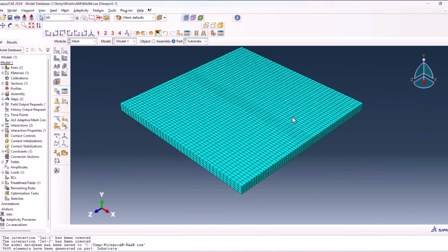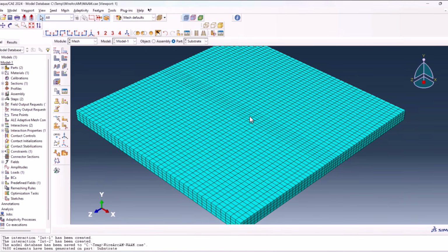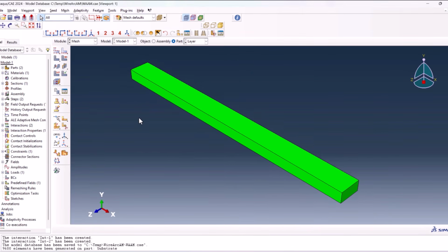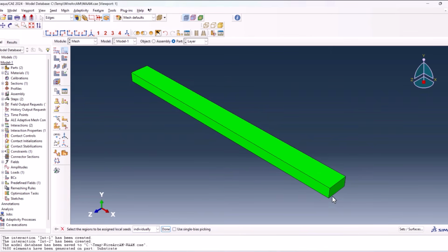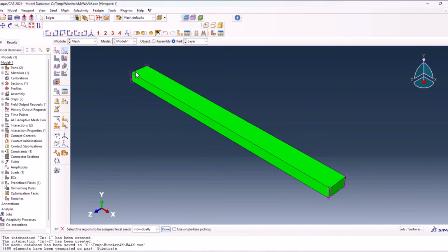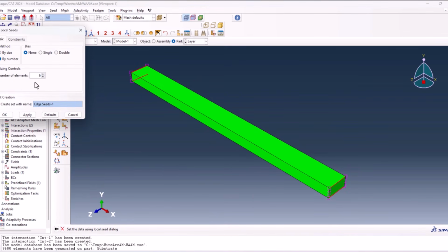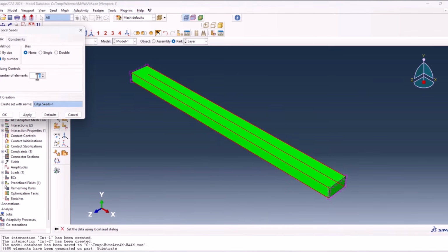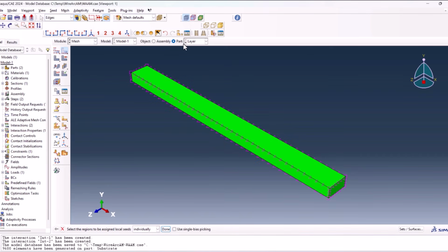Let's mesh it. This is the mesh. As you see here, we have a refining version in this direction in the middle. Now let's go to the layer and do literally the same thing. So this one, this one, this one, and this one. These should be 4. This one, this one, this one, and this one. They should be 6, and last but not least, these guys must be 40.